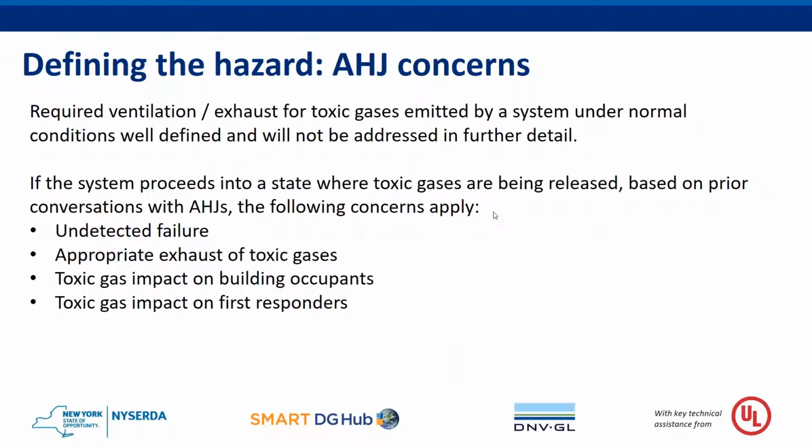So to outline what the hazard is as perceived by the authorities, one, it's recognized that gases from some systems are output under normal operating conditions, such as lead-acid systems. Those hazards are already very well defined and very well managed within code. So the building mechanical fire code already handles those items, and so we won't be talking about that. We will only be addressing concerns for hazardous toxic gases emitted during a fire event or other abnormal operation events.